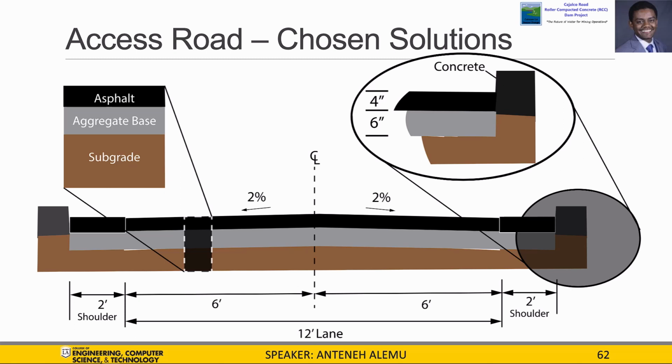These issues were mitigated by developing a road design with minimal distance and acceptable cut and fill located east of the RCC Dam at the curvature of the Eagle Canyon Road. Given the road design parameters, our turnouts and turnarounds are strategically placed to meet vehicle standards. This access road is mainly used for maintenance and possesses a low traffic volume, so we went with the asphalt